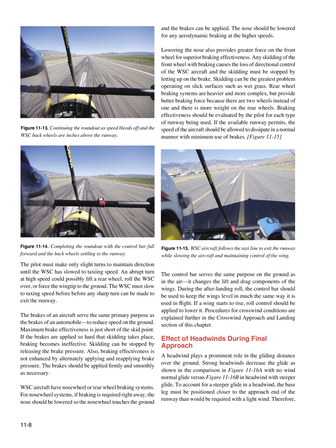The pilot must make only slight turns to maintain direction until the WSC has slowed to taxiing speed. An abrupt turn at high speed could possibly lift a rear wheel, roll the WSC over, or force the wingtip to the ground. The WSC must slow to taxiing speed before any sharp turn can be made to exit the runway. The brakes of an aircraft serve the same primary purpose as the brakes of an automobile, to reduce speed